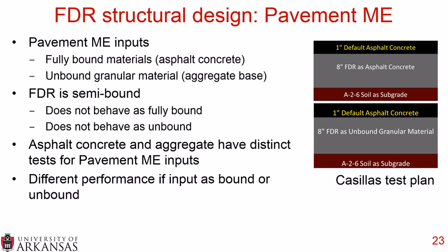So you have the same FDR material, but she ran two completely different sets of tests. One was the test for asphalt concrete, one was the test for unbound granular material. And she found that there was different performance if the input was a bound or an unbound material. So the exact same material, exact same design, performed differently in Pavement ME if you classified it as asphalt concrete or as unbound granular material.